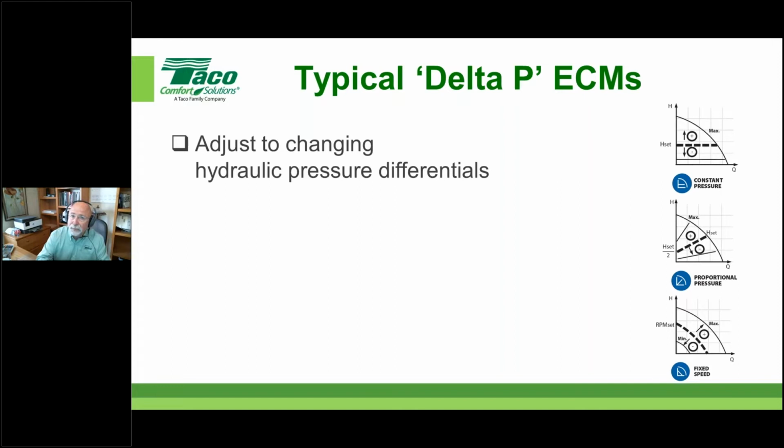We've got an impeller that's in the water, it's on a shaft, that shaft's connected to the motor, and that motor feels these hydraulic changes, and that's what it needs to make a decision, hence the name delta P, the pressure within that. Some people think these things have pressure sensors in them, and some do, and those can be problematic as well. So understand the motor, generally speaking, is what feels the change. We call it a pressure differential circulator.